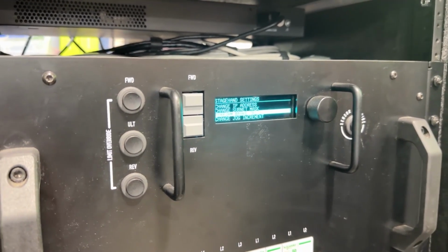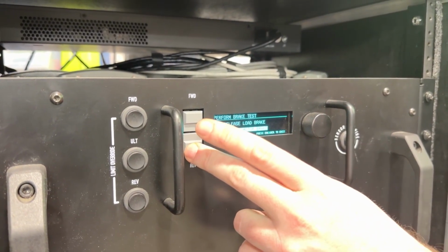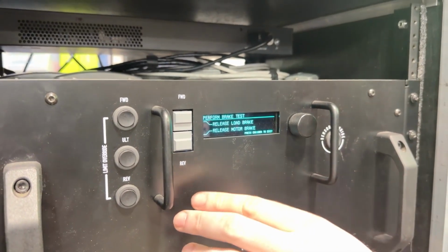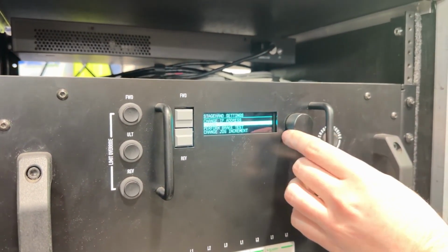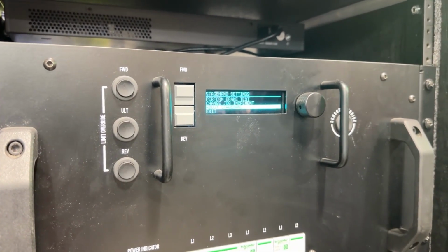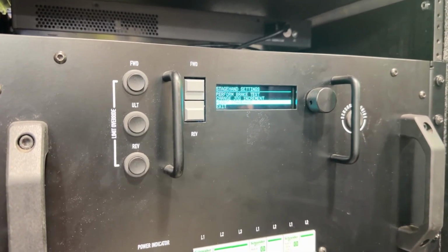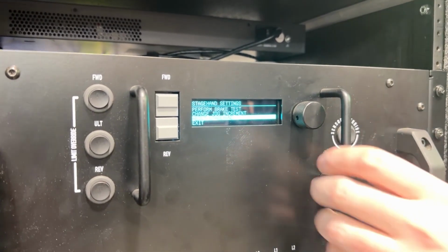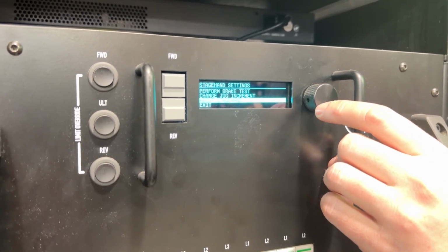The other thing you can do is, on hoists that have 2 brakes, you can also perform a brake test. So you can independently fire the brakes to ensure that they are working. The push stick doesn't have a load brake, so that's a pretty unimpressive button at the moment. But it's worth saying too that if you were to press both at the same time, it'll automatically engage both brakes, so you don't accidentally drop the load by trying to outsmart it. That is not the danger button. We've prevented that.